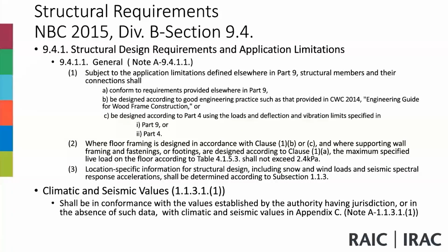Location-specific information for structural design, including snow and wind loads and seismic spectral response accelerations, shall be determined according to subsection 1.1.3. So if you're using location-specific information for those elements, then you have to use those as specified in 1.1.3. You need to refer back to them.